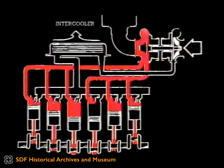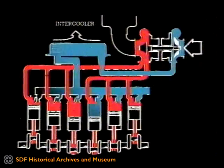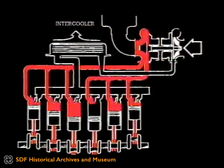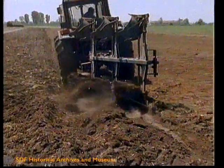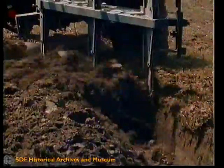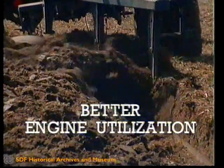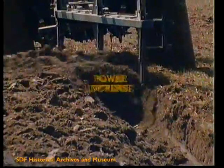Therefore, provision is made for cooling the compressed air before it is introduced into the cylinders. Intermediate refrigeration, intercooling, with the result that the density and the power generated by the engine are increased. The reliability achieved by the turbocharging systems makes their use continually more widespread, which offers advantages from many aspects. Better utilization of the engine, which offers lower specific consumption and greater resilience.